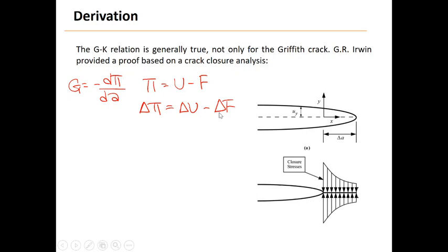Now, the change in work done is zero because of how we posed this problem: the plate is gripped at the top and bottom, and the grips don't move between these two configurations. Therefore there is no displacement of the applied force, and therefore no work done.